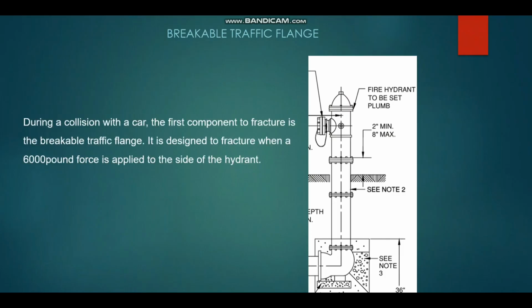So this point I told you, during a collision with a fire hydrant, the first component to fracture is the breakable traffic flange. So here you see this is the breakable traffic flange. Normally it is designed to fracture when a 6,000 pound force is applied to the side of the hydrant. So during an accident the force will be more than that, and if it is more than that, surely the first component which is broken here is the breakable flange.